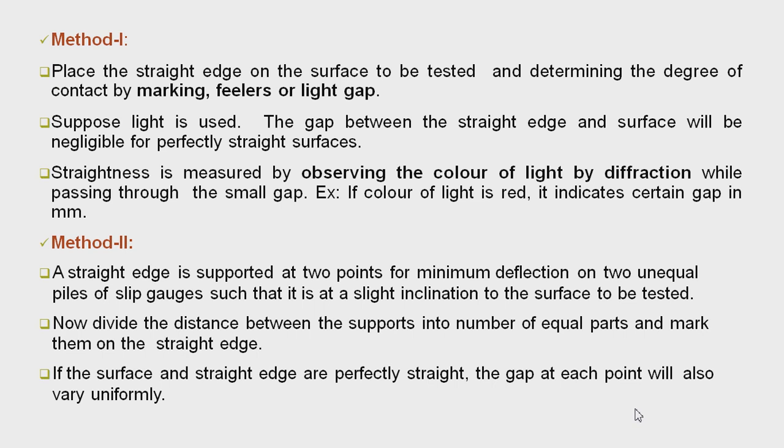Similarly, there is another method in which the straight edge is supported at two points for minimum deflection on two unequal piles of slip gauges, such that it is at a slight inclination to the surface to be tested, as shown in the figure.